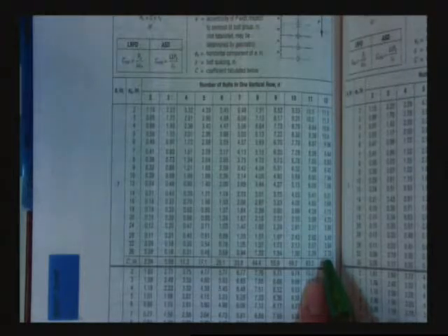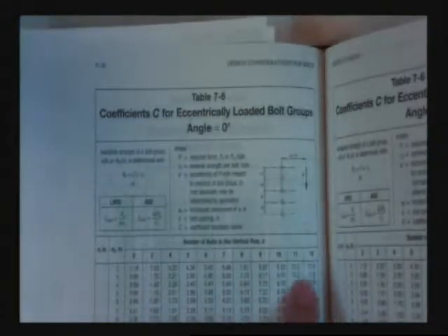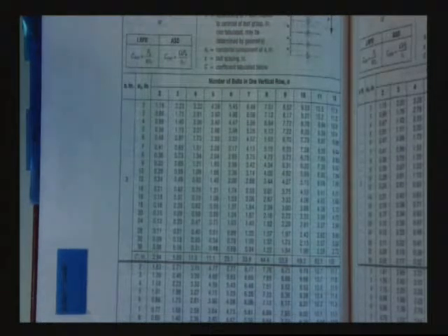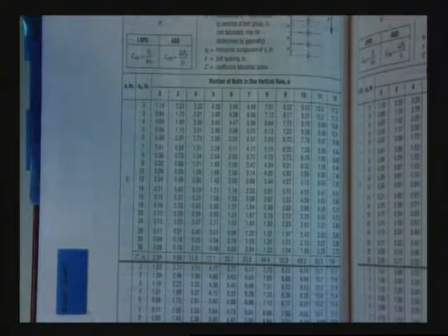2.7 bolts loaded concentrically. You with me? Okay? Now, as your spacing goes up, oftentimes your capacity goes up. Well, your moment arm gets larger, doesn't it? Your depth gets larger. So hopefully that makes sense. As your eccentricity goes up, the number of equivalent bolts goes down, right? Okay.